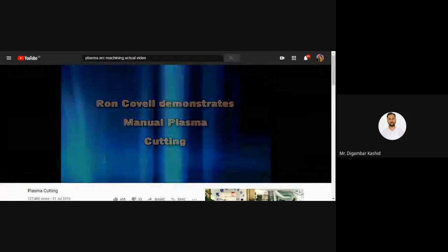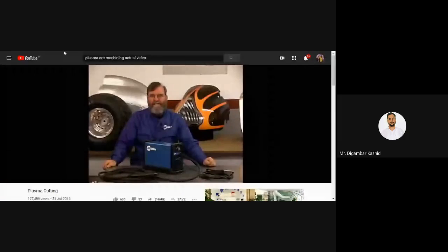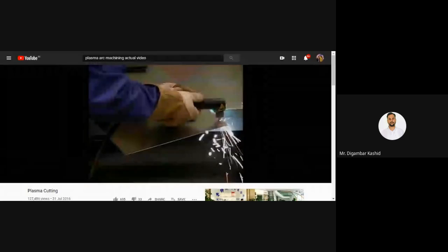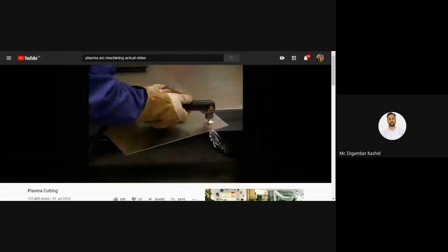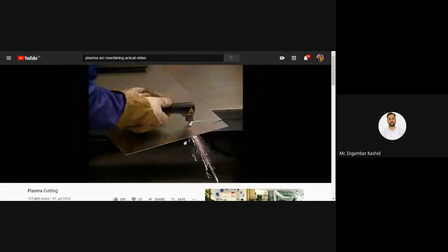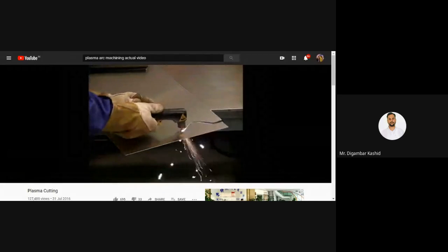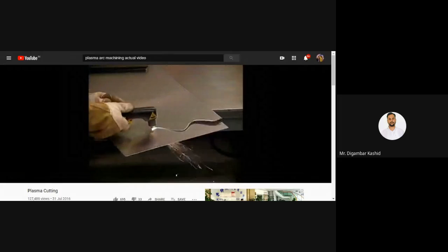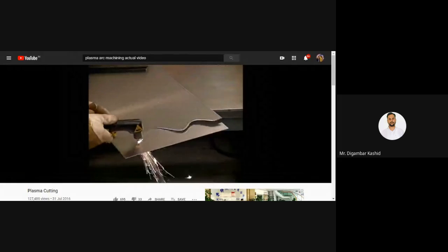Welders generally need to do a lot of metal cutting in preparation for welding. Plasma cutting lets you really zip across a piece of material, speeding the work and decreasing the operator's fatigue. This is plasma cutting. While it's certainly possible to do freehand cutting with a plasma torch, you can often get greater accuracy by using a guide.